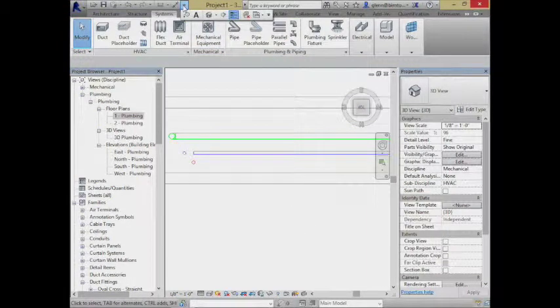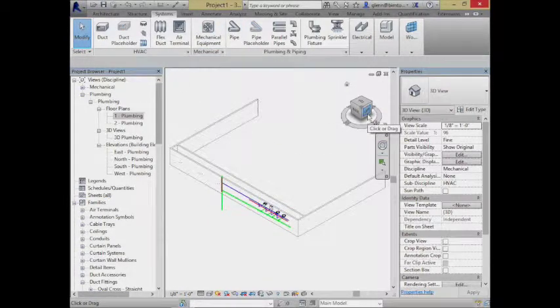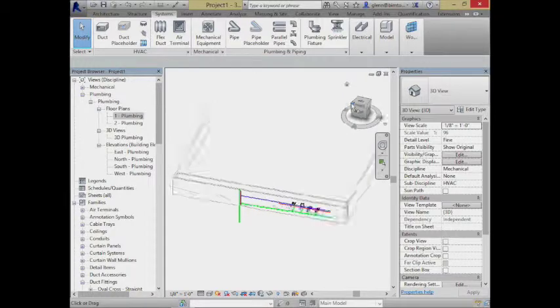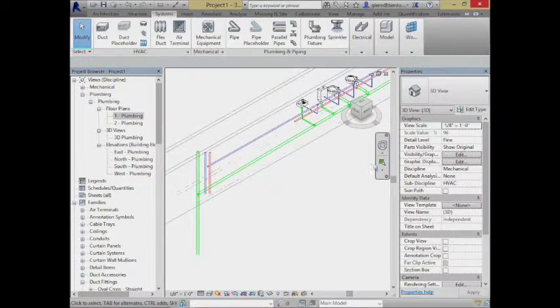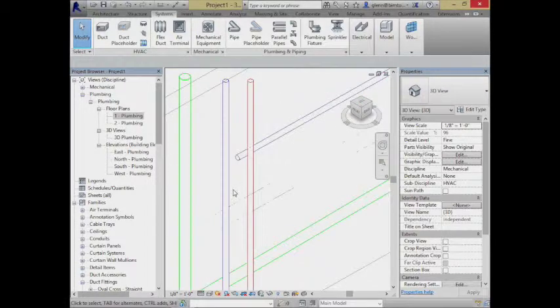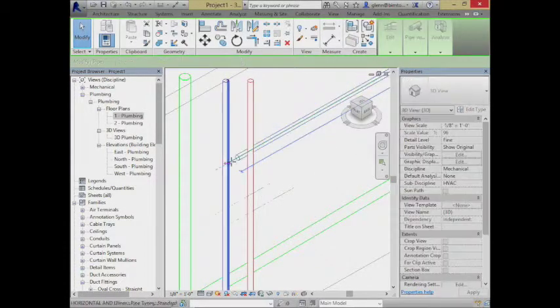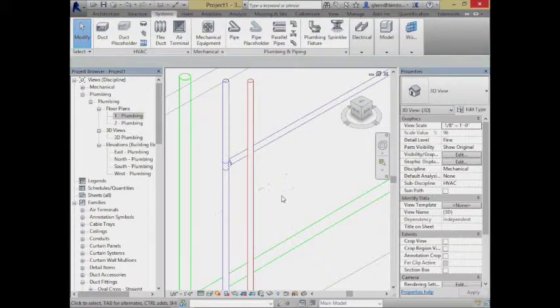So with those risers, let me flip that over. I can do the same sort of thing I did with the sanitary pipe. I can take that, pull it on over as soon as I get it to intersect. That's no longer an uncapped connection. It has some sort of T there.